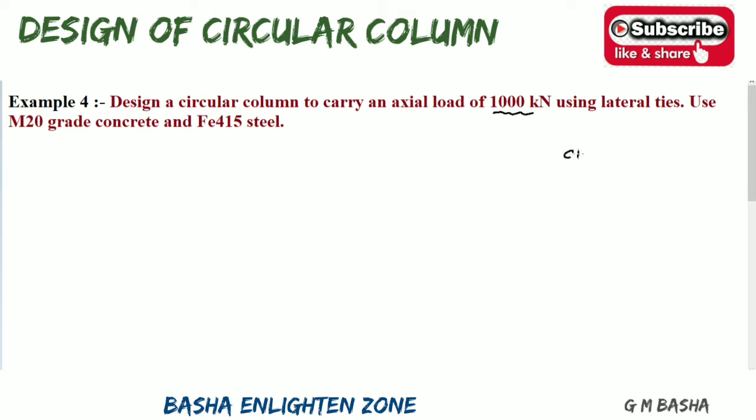So while talking about the circular column, we can use both lateral ties or spiral columns also, in the form of a spiral like this. So we have to provide spiral for the longitudinal bars. We will discuss that in the further classes. Here, by using lateral ties, we are going to design a circular column. We don't know the diameter of the circular column, so based on the given data, first we have to find it out.